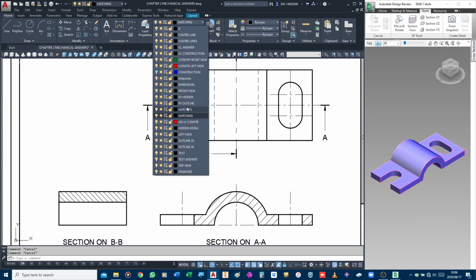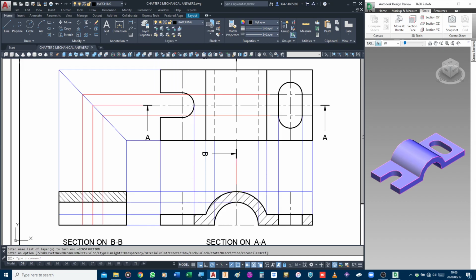Okay, now to finish off this left view, remember what I said to you last time? Center lines. If there's any feature behind any object that is shown by a center line, I need to show it. What does that mean? That groove lies behind my cutting plane. There's a center line for it. There's a center line for it. Which then means I need to put those two lines and this one as a center line.